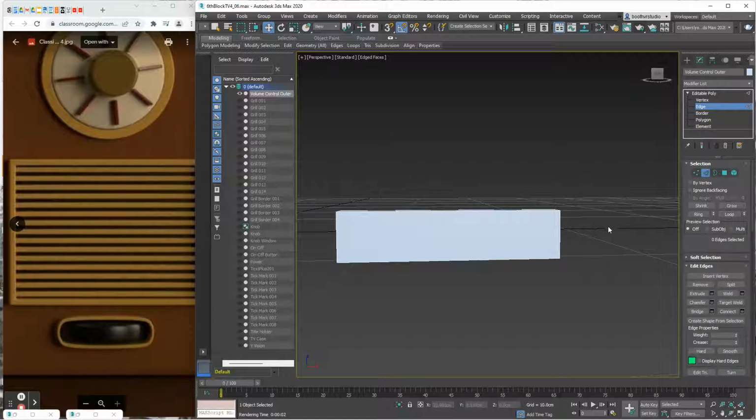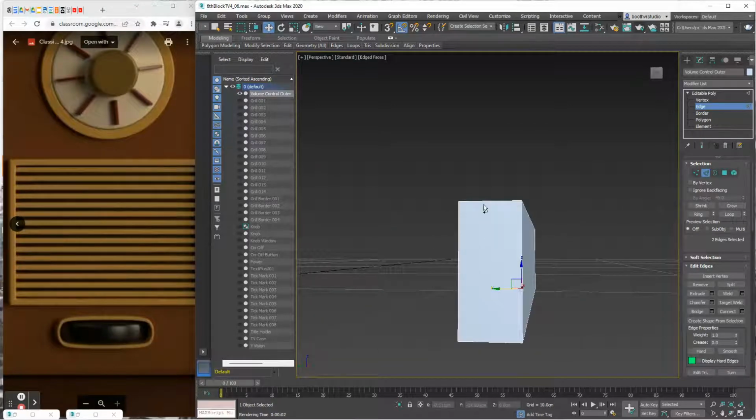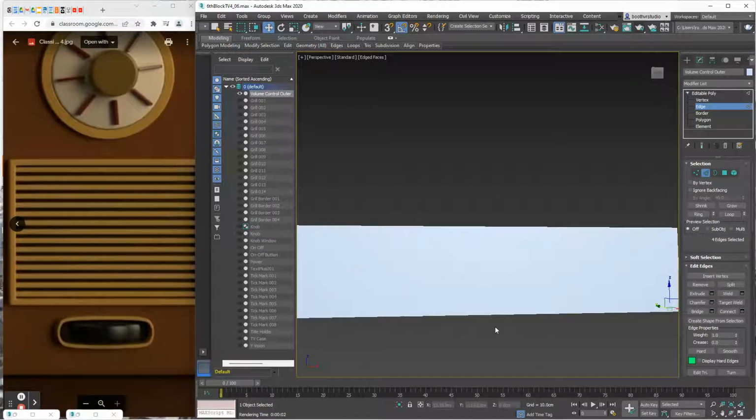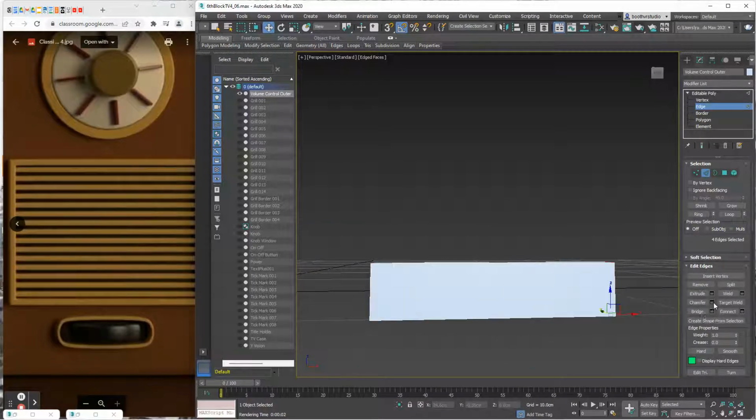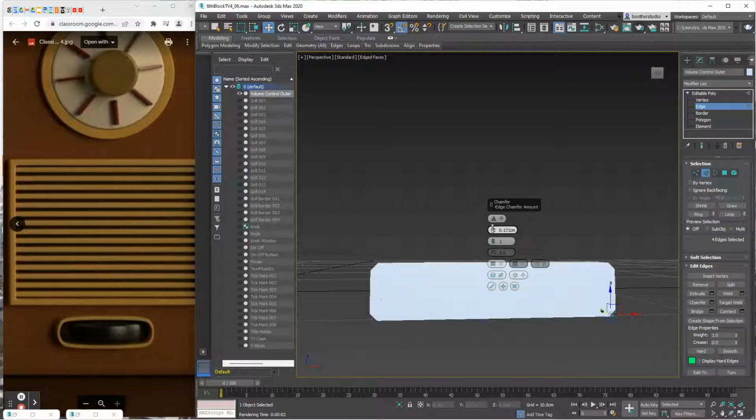And I'm going to get on its edges. And the edges I want to get are these edges here on the sides. And then I want to chamfer these edges. And just clicking the tool, of course, it really blows it up real fast. But if I change my number of segments to, let me make it 5 segments. Let me press the F4 key so I can.